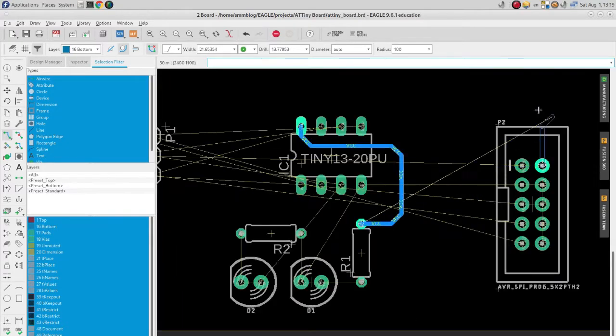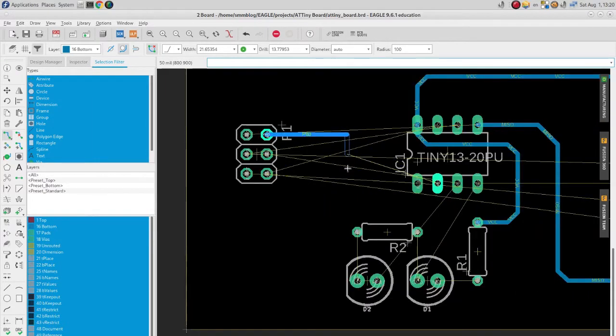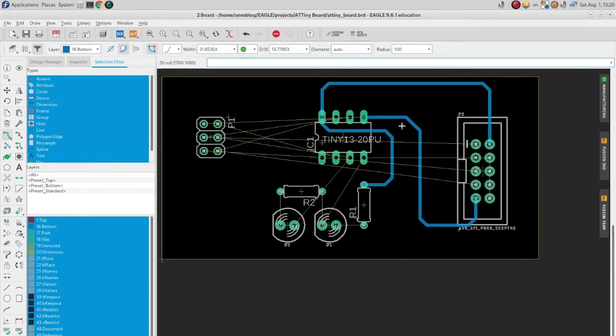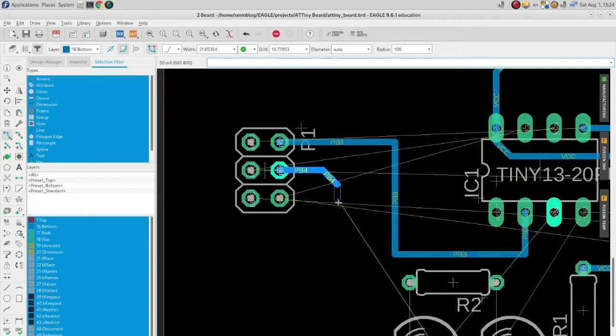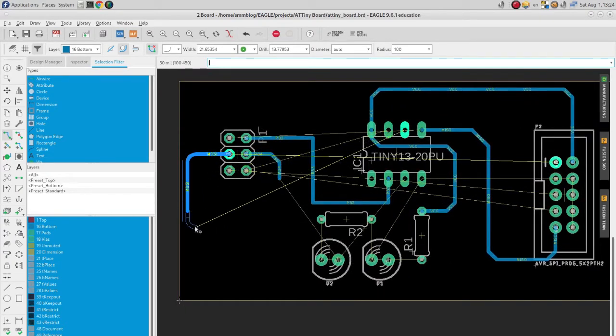I will now manually route these connections using some thick width copper trace. It's preferable not to use right angle traces because they can emit radio interference in FM radio PCBs or very fast computer boards. You could use 45-degree traces, which would be legit, or if you could do it, just use smooth traces, which are actually better, although some people might argue it doesn't matter at all.